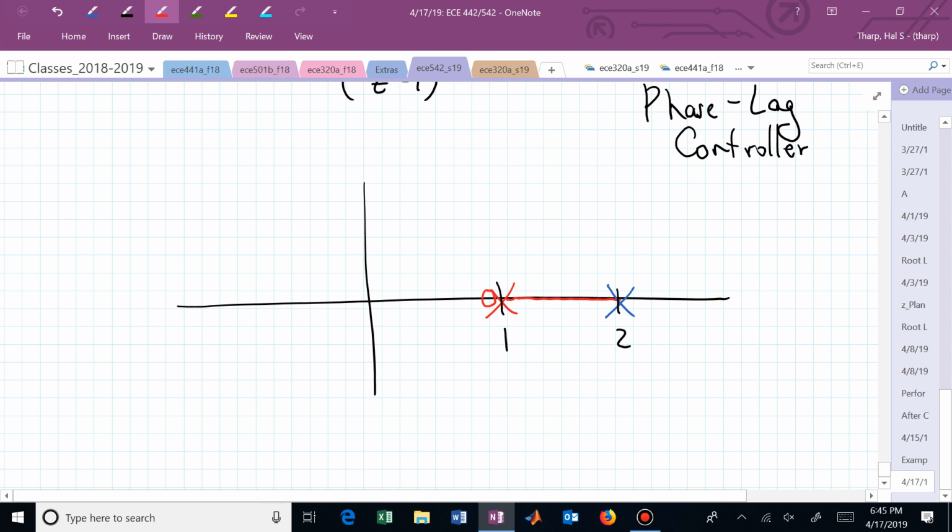What's the root locus of this look like? Well, that's our 2 poles and a 0. And this one probably is not going to be going very far. This now pops over so that we get a triangle there, and we know where that triangle is based on the selection of beta.